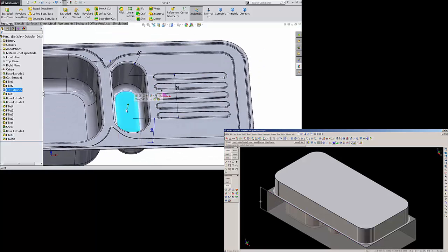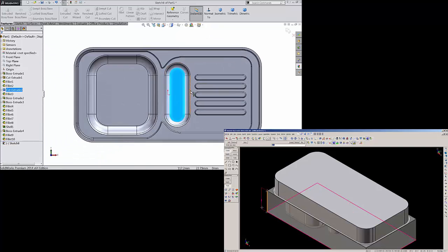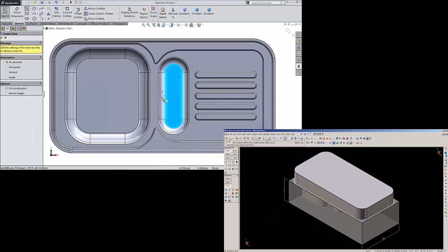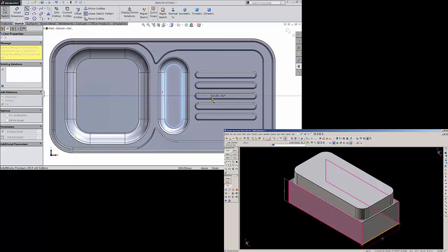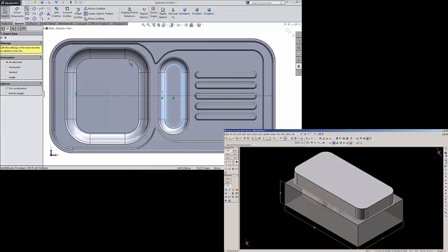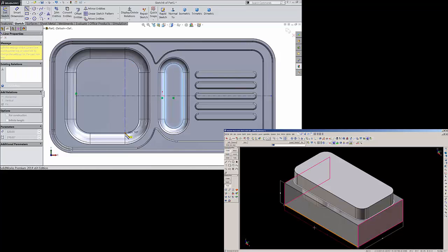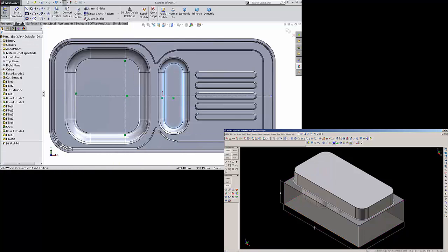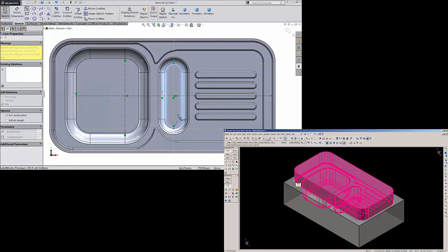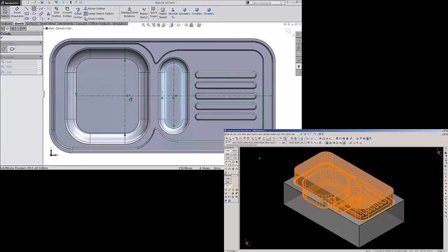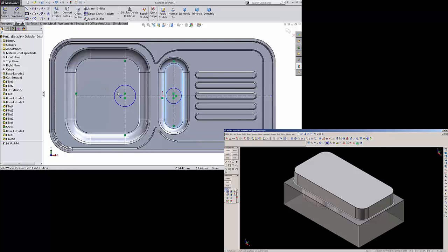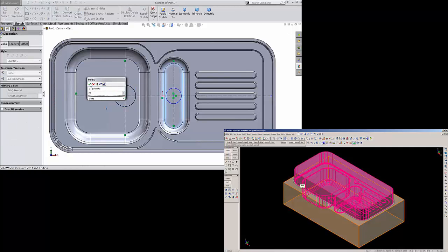Okay, now select this inside face, sketch normal. Now here we want to create a basin hole for water inlet and outlet, water outlet. Again choose a center line and draw one line. Let's make one more center line and draw a line from this center point. Exit. Choose circle and draw 2 circles. Let's keep this diameter 70 mm.